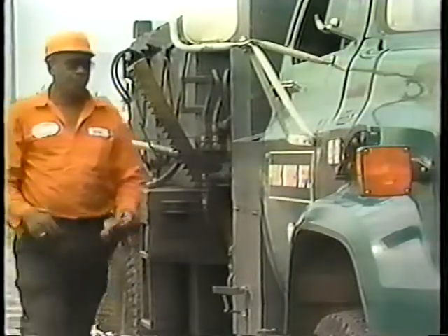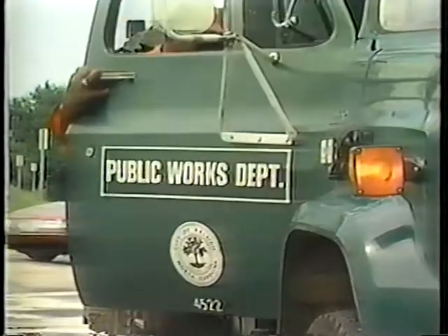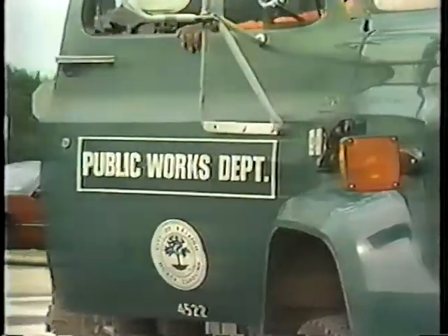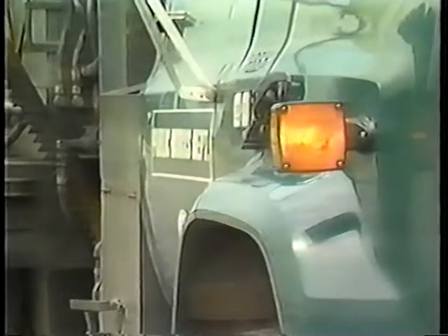The flashing lights should meet the requirements of the agency that has jurisdiction over the street or highway. These lights should be used in addition to other channelizing and warning devices. However, in some emergency situations where the work may be in progress for a very short time, these lights may be the only warning device.